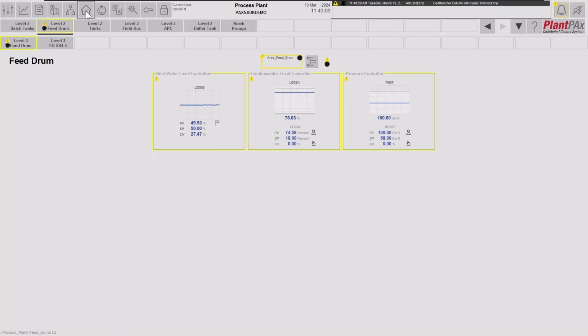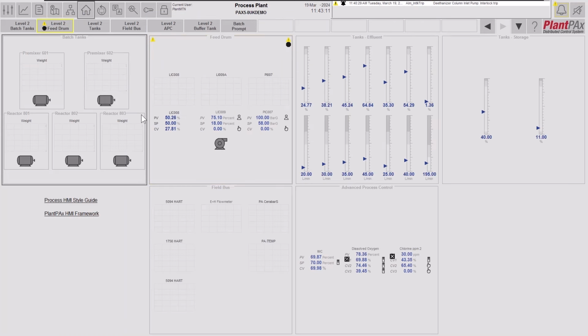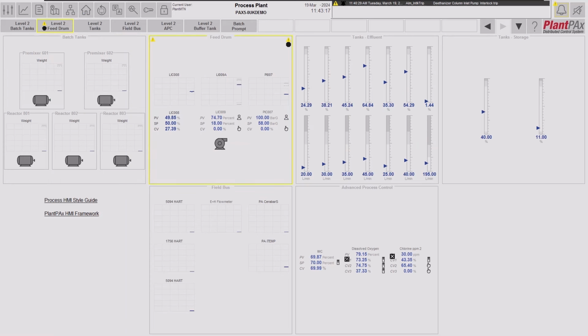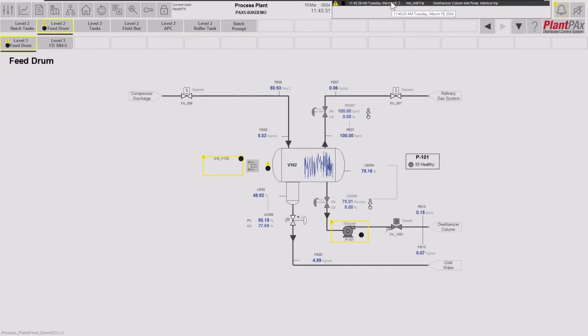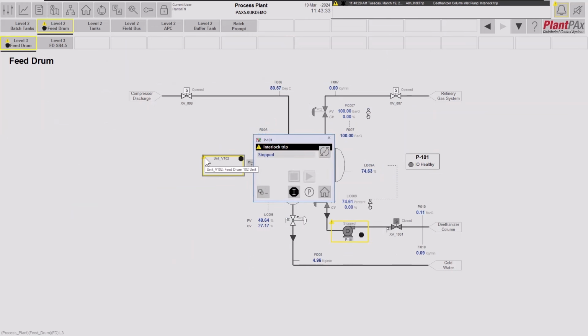Another option that we have is that the engineering tools that we provide with PlantPAx will set up the alarms for devices so that when we double click on them from our alarm banner or select them in the alarm summary and execute the command configured for them from here, they will take us to the display where the alarm is and bring up the faceplate.